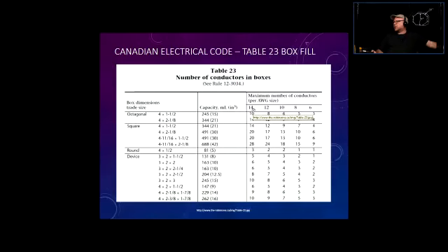But as the wires go thicker, we are able to fit fewer wires in order to be legal. For 12 gauge conductors, we can fit only 8. Then gauge 8, 5, and gauge 6, which is quite thick. You're not going to see much of that. This one is listed for only 3 conductors.